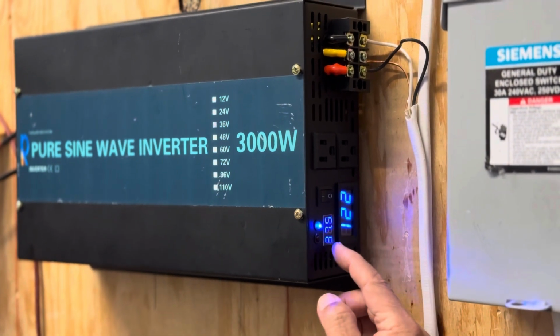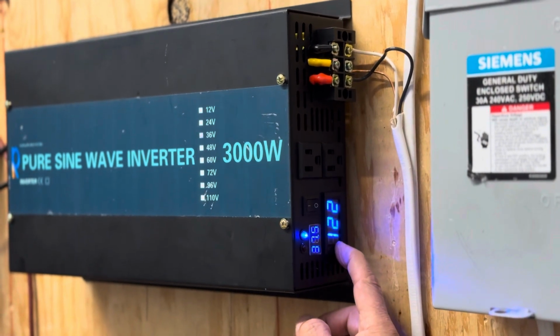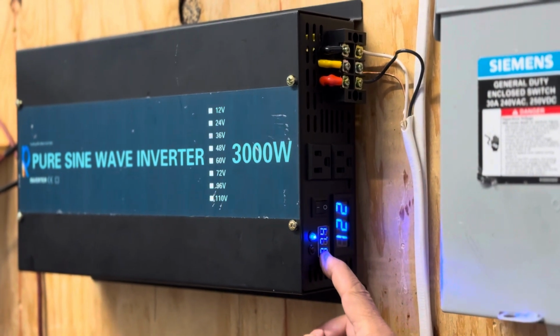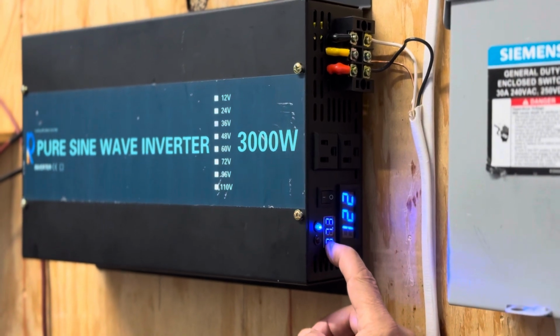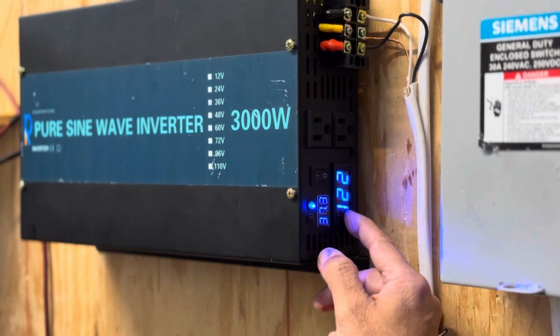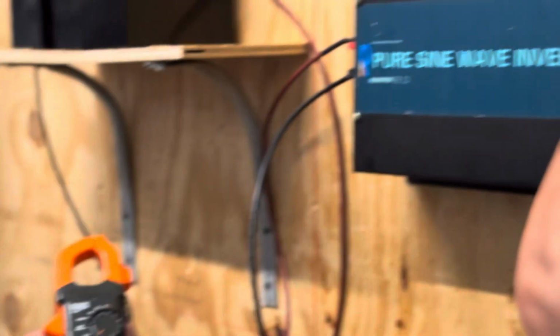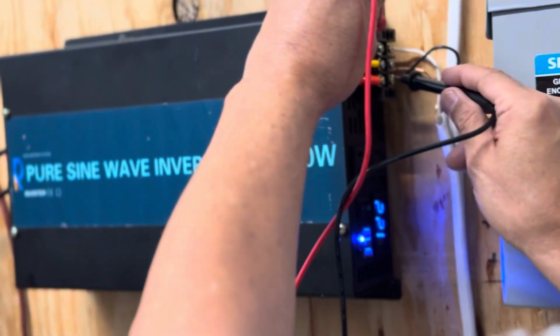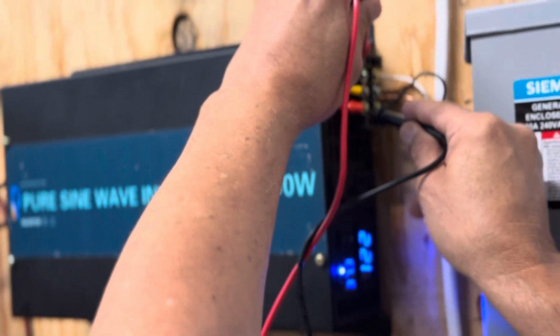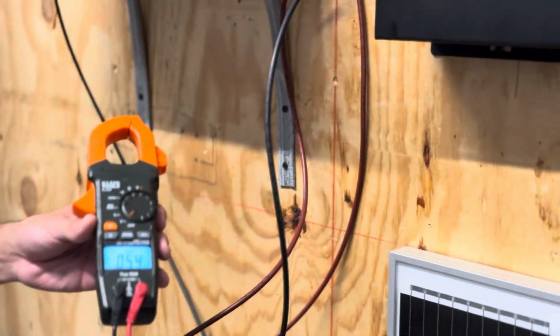The display is telling you the input, which is DC, and the output, which is AC. So 37.3 volts DC are converted into 122 volts AC. So I will check the output. My black one is the neutral, the red one is the hot, and I have here 120 volts. The yellow one here is my ground.